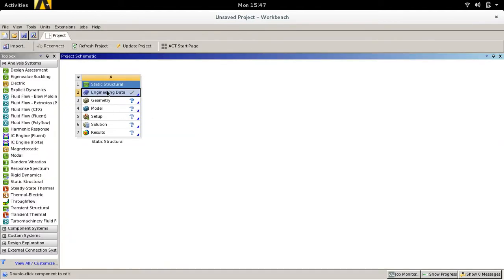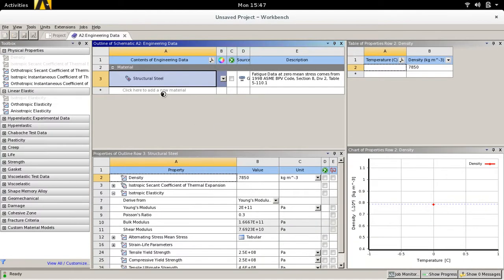Now I am going to teach you how to model concrete in Ansys. There is no default concrete model for Ansys, because the tension zone and compression zone of concrete are entirely different. It can take a lot of compression load but not tension load. So I'm going to model concrete by using commands, because we need to incorporate the concrete model by using commands. So in order to start, first I'm going to create the material.